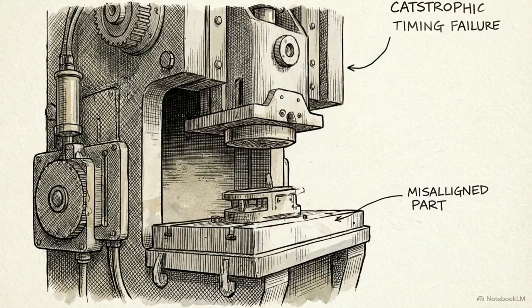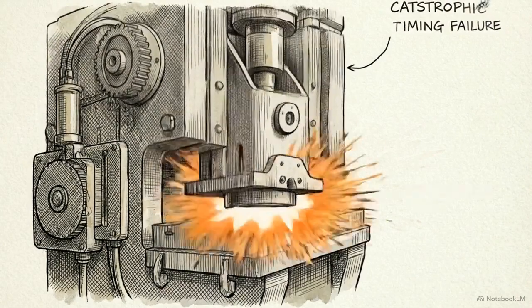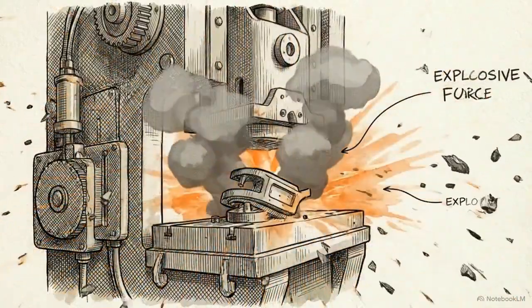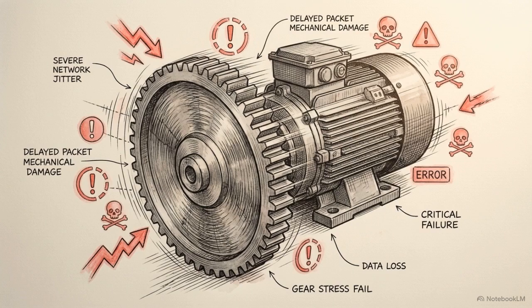However, that acceptable 2-second latency becomes a catastrophic failure if the requirement shifts to time-critical actuation and closed-loop control on the factory floor. Relying on a cloud server to execute a round-trip command for immediate mechanical braking introduces network jitter. If a packet is delayed by milliseconds, the machine damages itself.